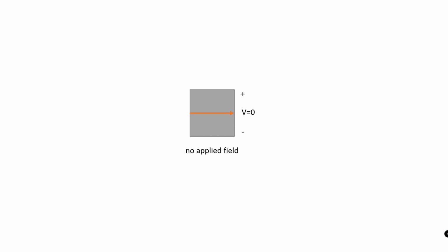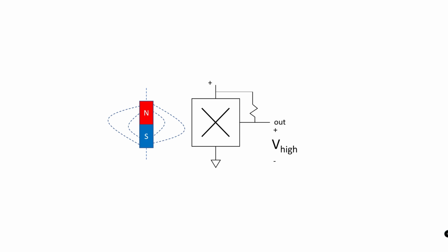Door sensors like those in cars are often built using Hall effect sensors. In a Hall effect sensor, a current flows across a metal patch from one edge to another. When a magnet is placed near the bar, its magnetic field causes the current to bend, resulting in a voltage across the sensor. Here's the circuit used to translate the Hall effect sensor output signal into a digital logic value.